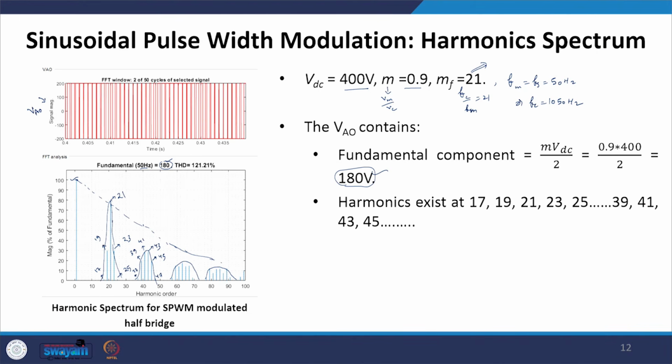So in this lecture we have understood the concept of pulse width modulation, where the pulse width of the pole voltage varies, and that is why it is called pulse width modulation. We can vary it in proportion to the amplitude of the modulating signal, and that is when we can get any average pole voltage variation, which could vary sinusoidally or with different frequencies. However, one condition is that we must ensure the frequency of the modulating signal is very much smaller than the carrier signal frequency.